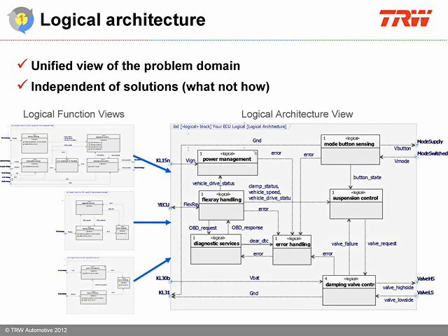As we iterate through the use cases, the functional behavior of the ECU functions is gradually integrated into a unified logical architecture. We can create an integrated view of the whole logical architecture, since the diagrams in SysML are just that, views into the architectural model. The logical blocks are abstract to any physical solutions and only represent the logical functionality required to perform the ECU functions. The only physical influence is the ECU's interfaces to the outside world, since these are a given solution and not for debate. The logical architecture provides the infrastructure for creating the physical architecture.